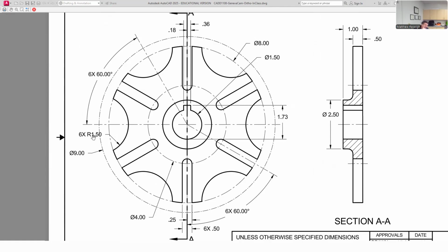So I might work on that a little bit. For metric prints, the way we set the dimension style is it pulls from the center and it includes the center in the dimension. I might adjust this one to do that for this particular dimension. I might just spot adjust that to say pull to the center, so it's obvious to the viewer that that's the center of that 9-inch diameter. So it's kind of critical to know that.